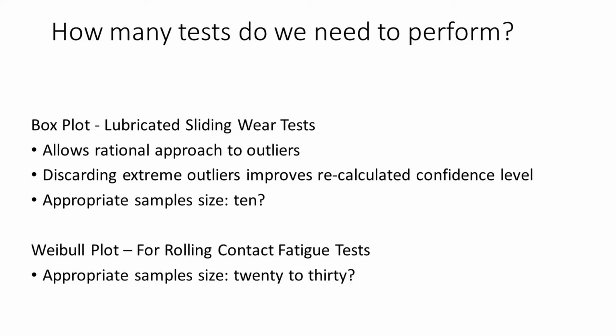Depending on the required confidence level, a minimum of 10, but more usually 20 or 30 repeat tests may be required. In the case of rolling contact fatigue of bearings, it is normal to present results in the form of a Weibull plot.